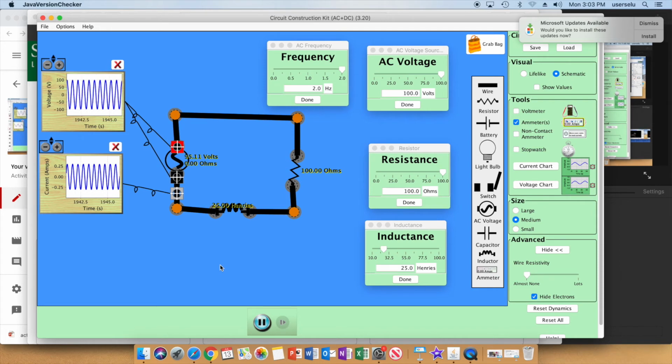Okay, now again, when you connect a resistor and an inductor in series, you can't just sum their resistances as you would for normal series resistance components. There's a phase difference in the relationship of their currents. They are again 90 degrees out of phase. So essentially what you have to do is a Pythagorean theorem, a squared plus b squared to get c squared, to get the total resistance of this circuit. So again, you can turn to the slides for some more information on that. I can take the inductive reactance value, square it, add it to the square of the resistance, take the square root of that, and that'll give me the series resistance of these 2 components.